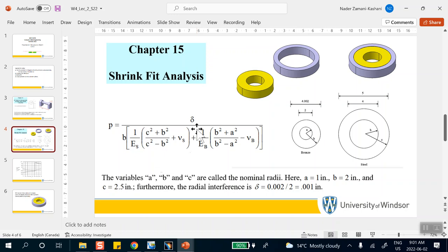Yeah, that's it. You heat up the outer ring, it grows, or you put the inner ring in the fridge, in the freezer. It contracts, and then bring it out quickly, stick it in there, and let it go back to where it goes. That's called shrink fit or pressure fit. Yeah, both of these terms are used. I think Katia calls it pressure fitting, but don't get hung up on the terminology.